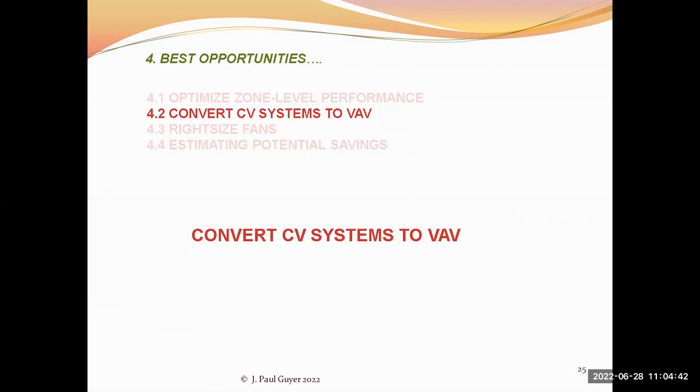Now, the difficulty that may very well arise is that if you do that, then the zones, what are now the new VAV zones, are now fighting each other for air, and this is a place where a lot of energy gets unnecessarily used.